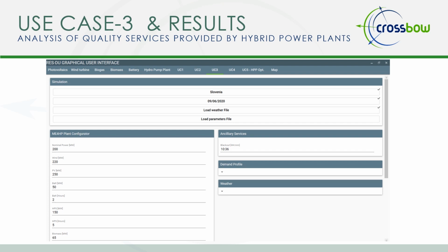The purpose of the restoration service is to restore the power supply in case a disturbance on national or regional level appears. It's based on the ability of certain generator groups to start without any external power supply after a zero voltage in the installations.